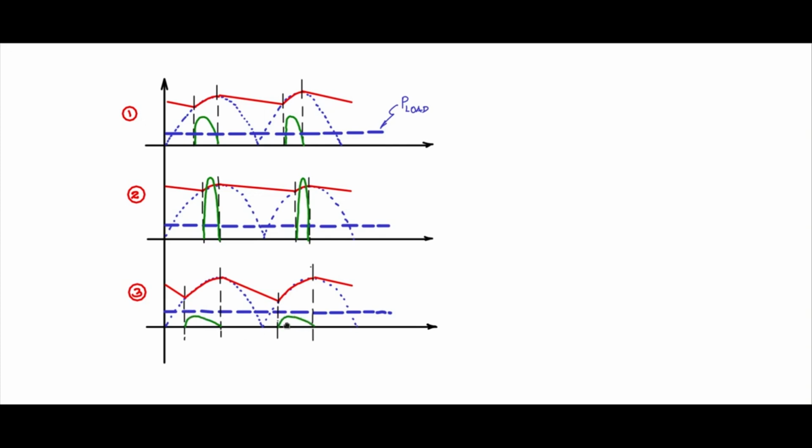So this is actually the concept that we will be using in passive power factor improvement. We will be trying to increase the current conduction time at the expense of more ripple, and thereby reduce the current peaks and improve the power factor, making it closer and closer to the full conduction as in the case of a pure resistive load.